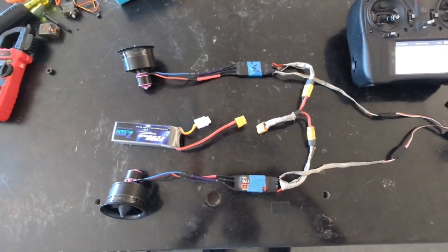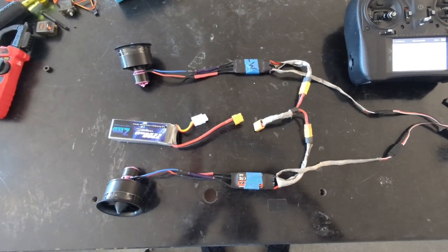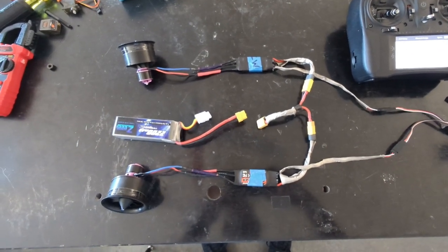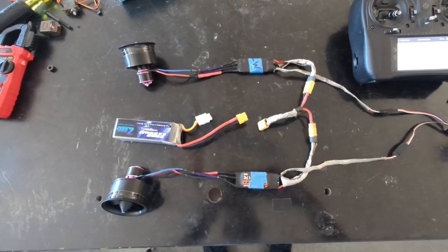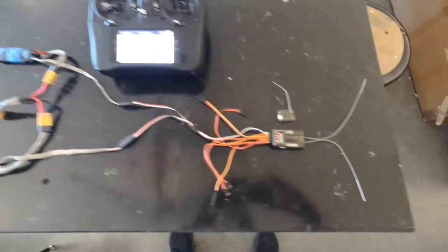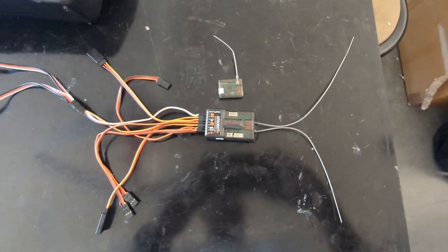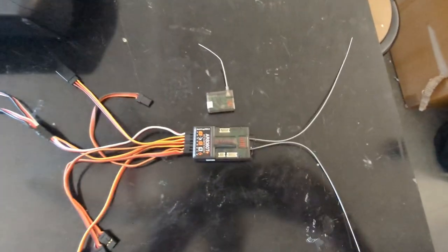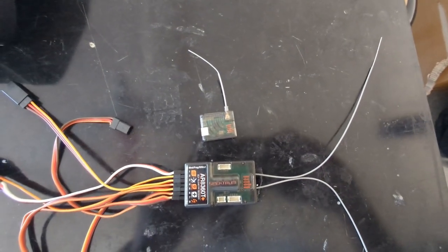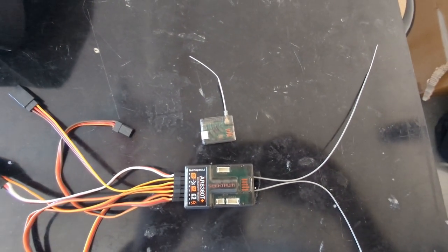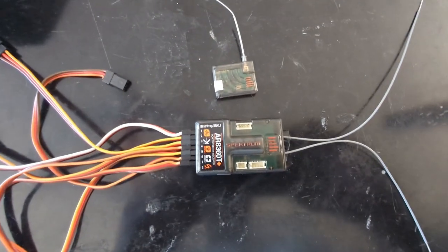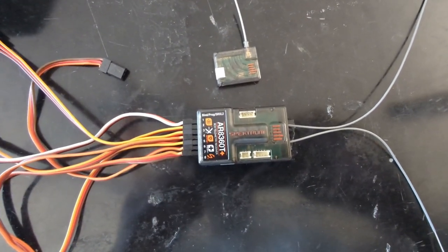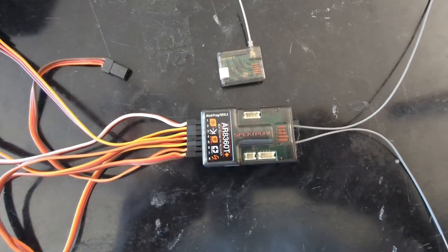Each motor is controlled by an electronic speed controller, or ESC. Each ESC draws current from our battery and powers its respective motor. Each ESC also separately powers our RC receiver, which sends PWM signals back to each ESC. The RC receiver goes in the nose cone, and we also have a separate receiver that goes in the tail cone to provide more RF coverage. Each of our 7 control surfaces is assigned to a separate port on the RC receiver.